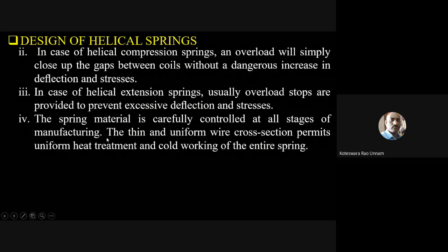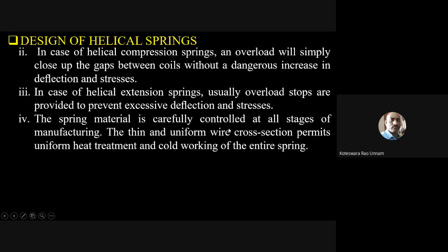Even from the material point of view, the springs are manufactured carefully in a controlled manner at all stages of manufacturing. It is also heat treated uniformly, and that means while manufacturing the spring, a lot of carefulness will be used so that there is uniformity in the material for the entire spring. That means the uncertainties in the material composition will also be very less in case of the springs. So therefore, you don't require very high factor of safety.